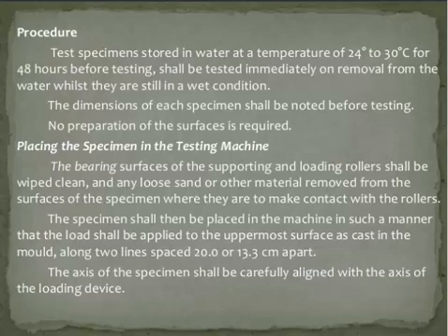The specimen is placed on the loading points. The hand finished surface of the specimen should not be in contact with the loading points. This will ensure an acceptable contact between the specimen and the loading points, and centers the loading system in relation to the applied force.